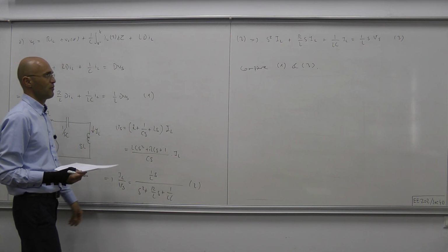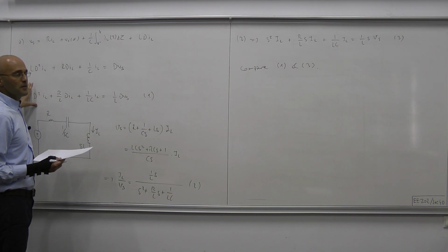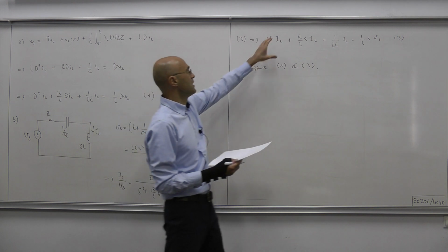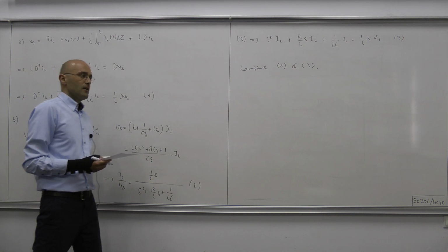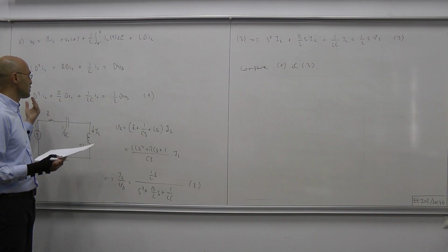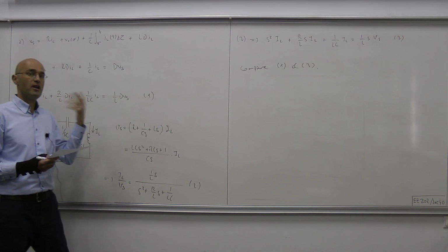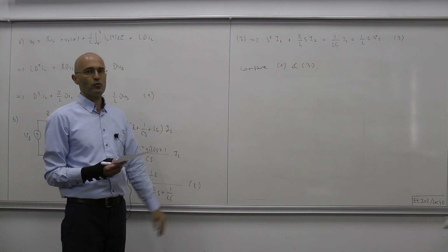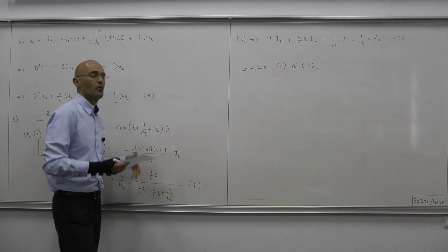That means if you have the transfer function, or that equation, which is more or less the same thing, from that you can obtain the differential equation describing the relation between the input and output in time domain, or vice versa. If you have the differential equation, you can easily go to the transfer function representation. The reason is obvious: if you have this equation, transform both sides using Laplace transform. Since we're trying to obtain the transfer function, by definition all the initial conditions are 0. When that's the case, it's really easy to obtain the Laplace transform of the derivative operator. Whenever you have a differentiation operator d, replace it with s, and you don't have to worry about the initial conditions. They're all set to 0. When you do that, you automatically obtain this equation, or in other words, the transfer function.